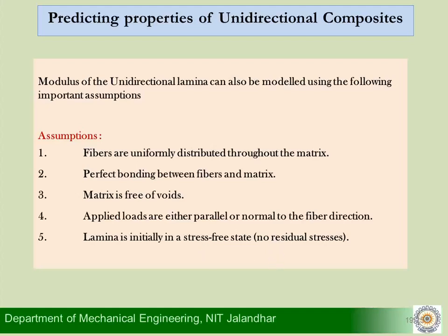There are no residual stresses, which may not be true in many cases, because we understand that the fiber and the matrix have different properties. When they solidify, when they cure, they have different thermal expansion coefficients also, and because of the exothermic reaction that happens in most thermosetting resins, we find that shrinkage stresses are normally developed in composite materials.